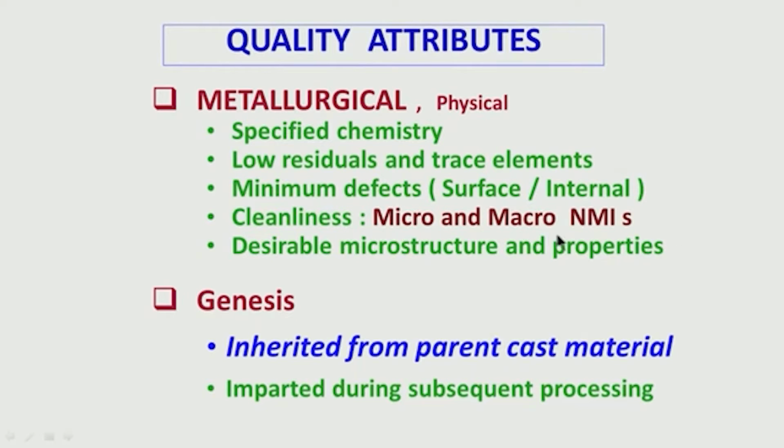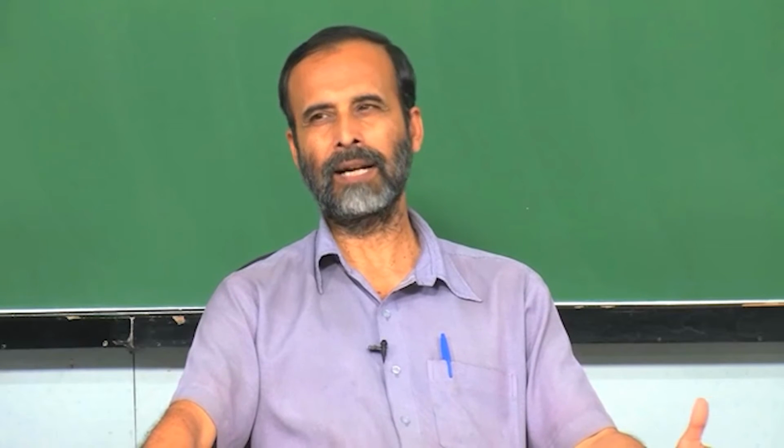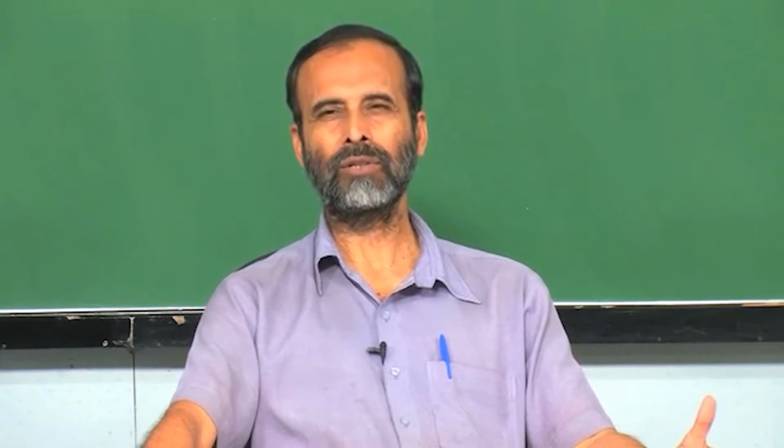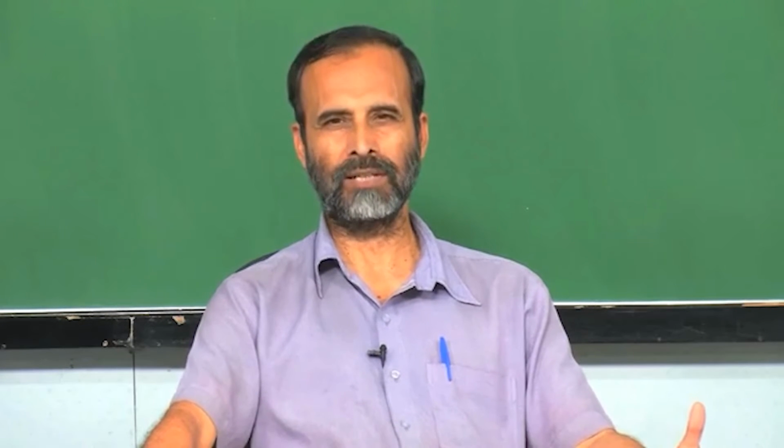Then I talked about the micro and macro NMIs, non-metallic inclusions. These are called non-metallic because these are not elemental, like iron or sulfur or phosphorus. These are basically sulfides or oxides. So, these are non-metallic inclusions.